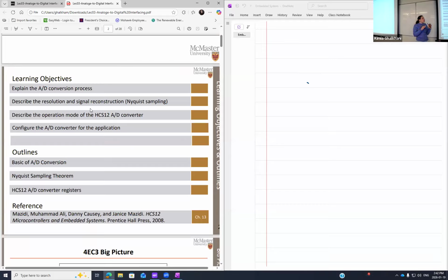I said initially set the resolution for 8-bit. Remember, yes, your microcontroller is an 8-bit register, but resolution is different. Sorry, I lose the words. Resolution. You can increase it. You can set it to 10.